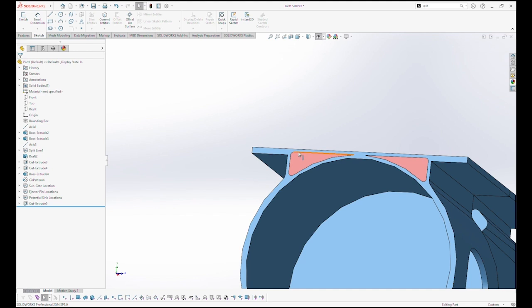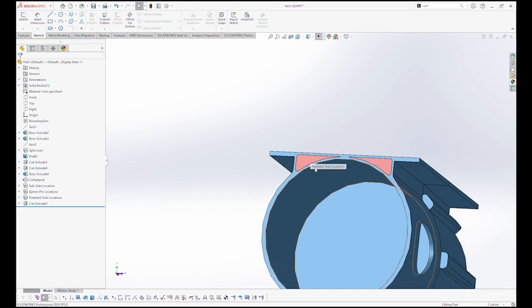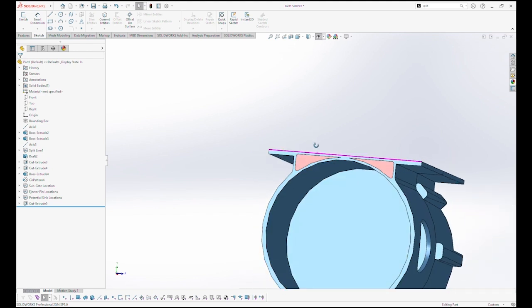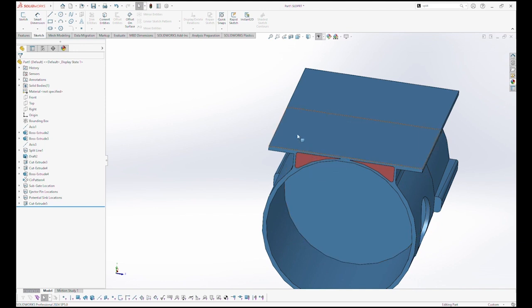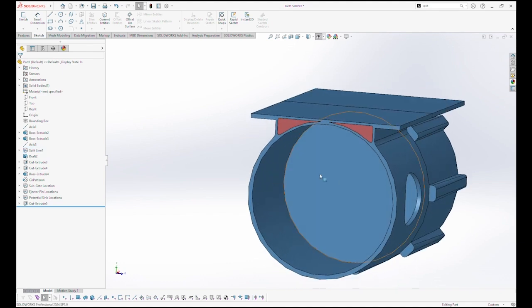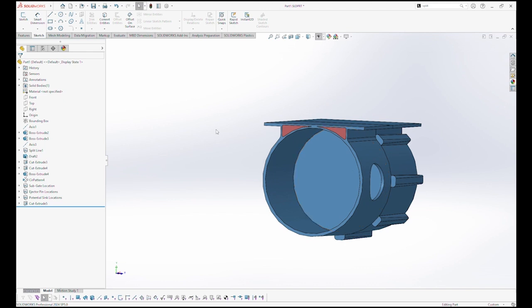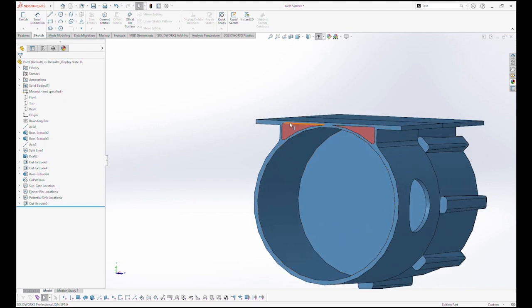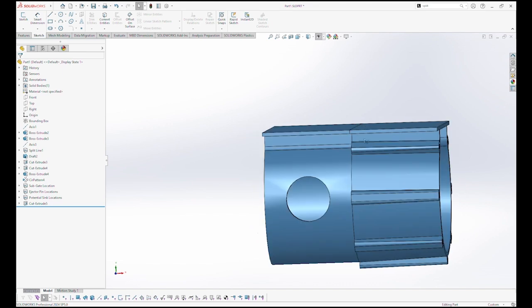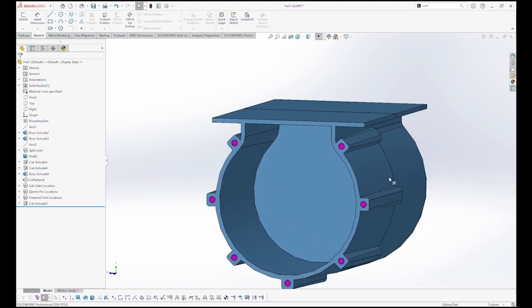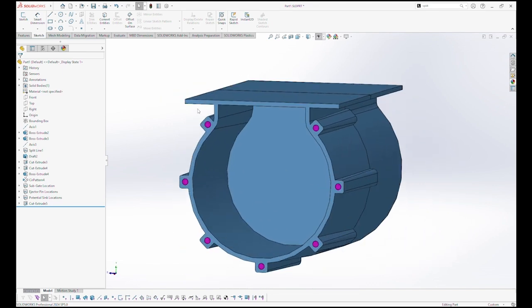And what ends up happening is that there's a sink that gets created there, and that sink usually means that it's going to pull the geometry around the part with it, and then it'll create some warp in the part as well. And so as you're designing parts, just look for these wall thicknesses that have gotten a little bit thicker. And as a contrast, we look at this opposite side, and you can see that we literally have a 10 thousandths wall all the way around, except for where the ribs are.